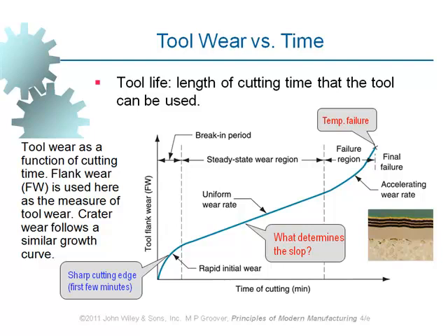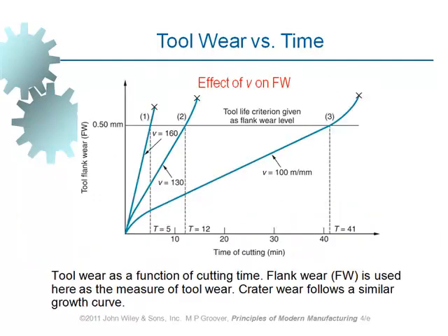It's the cutting speed. Meaning that if we increase cutting speed, what happens to this line? What happens to the slope? Would that be increased or decreased if we increase the cutting speed? Yes, it becomes steeper, and eventually, if it moves up like that, we reduce the lifetime of the cutting tool significantly. Let's take a look at this slide here, which is telling us more about this.